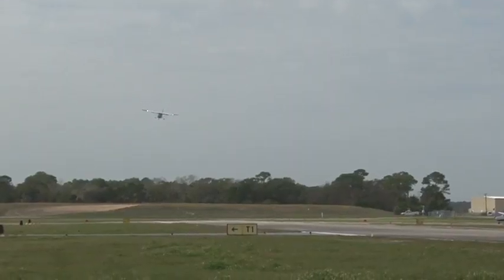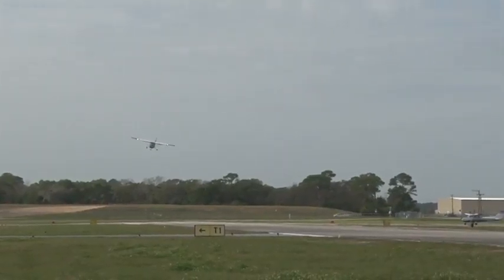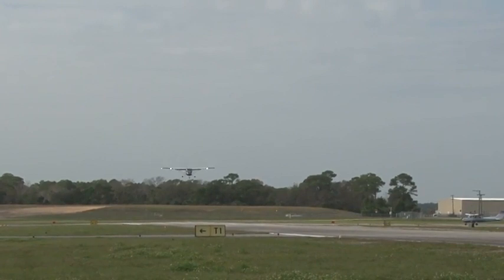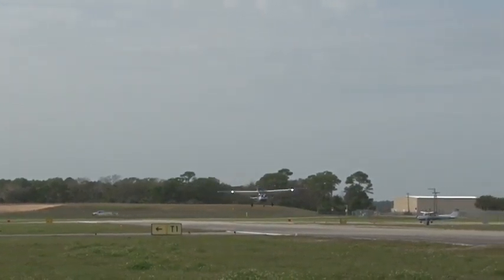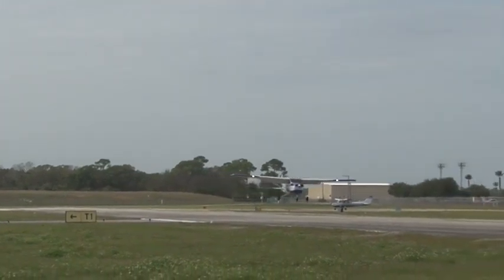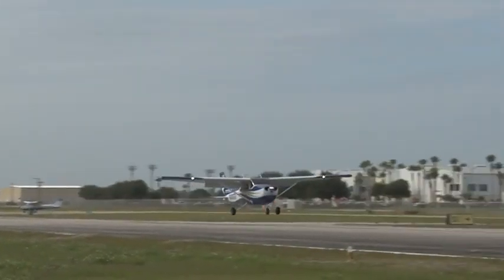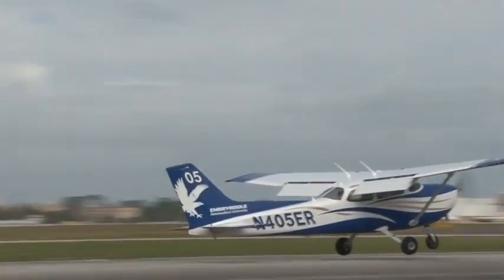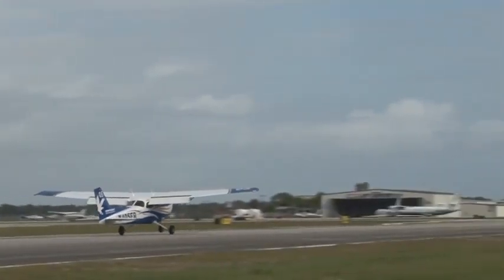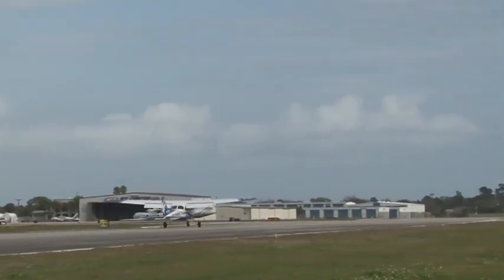High-lift devices such as flaps are designed to increase the lift and drag generated by the wings at low airspeeds. Flaps are particularly important for the approach and landing phases of flight. Use of flaps during a landing allows the pilot to fly at a fairly steep descent angle without gaining airspeed, and allows the airplane to touch down at a much slower airspeed.